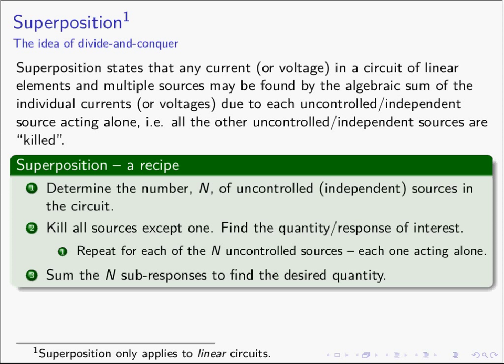So in our particular case applied to circuits, let's say we have a complex circuit, a very complicated circuit topology, and we're looking for a voltage or a current. And so superposition says instead of finding that voltage or current of this complex circuit topology using nodal analysis or mesh analysis or something like that, we are going to take our problem and break it into a bunch of smaller problems. Hopefully these smaller problems are simpler, and we will find some answers in the smaller, simpler problems, and they can be combined back together to give us the answer to the big problem that we wanted originally.